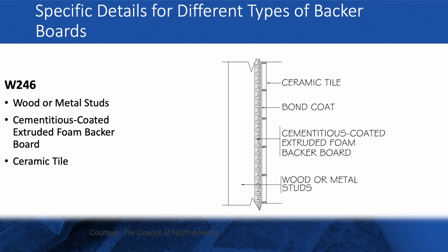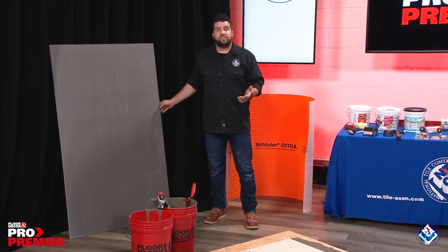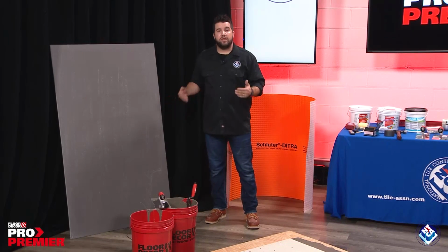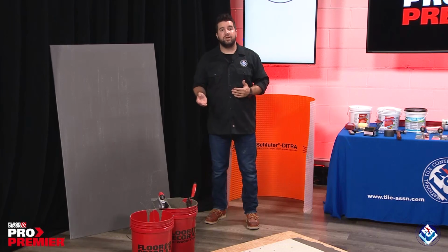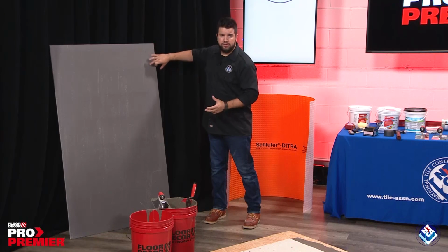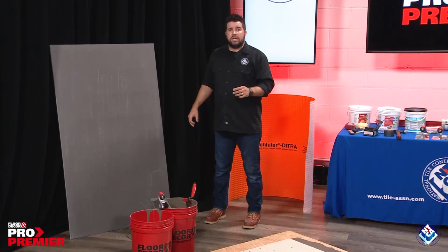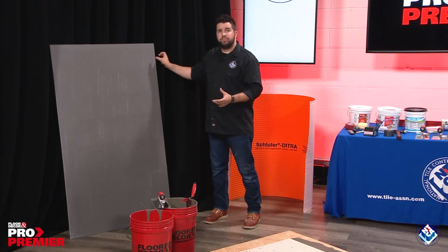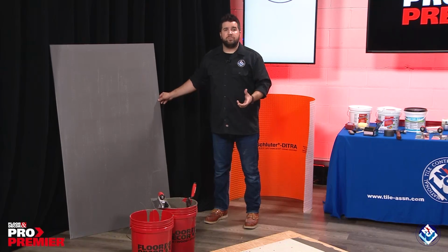Cementitious coated extruded foam backer board is installed fitting ends and edges tightly together, including inside corners. Apply a bead of the manufacturer's recommended sealant in the panel joints as the panels are being installed, and over fastener heads and washers per their recommendations. Also, some manufacturers may want us to put a piece of banding over top instead of the sealant. If it's not in a wet area, the joints can also be taped with a 2-inch alkaline resistant fiber tape and the cementitious bonding material.